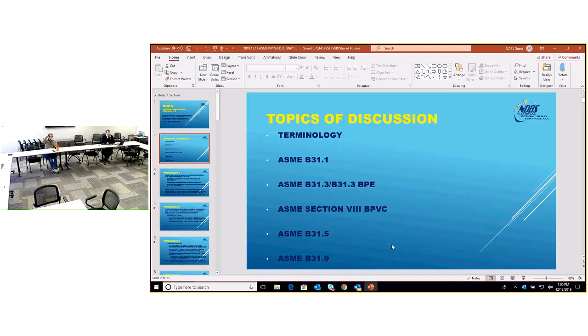So what I wanted to go through today was some basic terminology. I then wanted to cover ASME B31.1. I wanted to cover ASME B31.3 and B31.3 for BPE, which is higher purity piping systems, biopharma. I wanted to touch on the Section 8 BPVC, the boiler pressure vessel code. I've got a couple slides on ASME B31.5 and round it out with ASME B31.9. So let's jump right into the terminology. This will be the third slide.